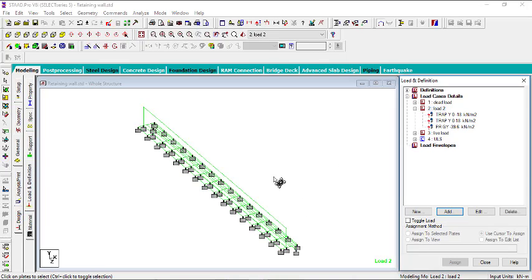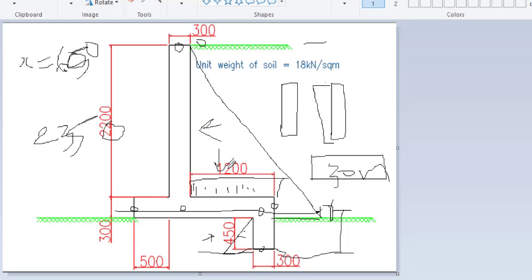However, we will still be having live load, a live load that will result due to rainfall. When rain falls, you will be having more load because of the soil. Let me show you the picture. We have a backfill here, which is a soil, which can be a cohesive or a cohesionless soil. But when rain falls, definitely the soil is going to absorb water, and then the weight of the soil will increase. Thereby, there will be more load on this stem, which is the wall, and there will be more load at this portion of the base. So that is the concept of the live load.